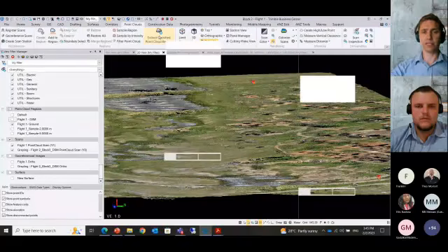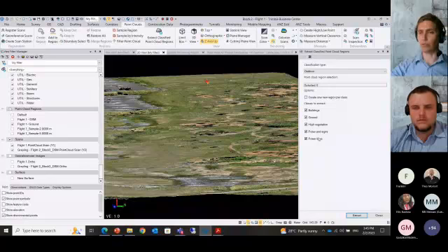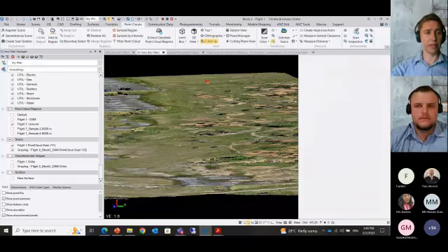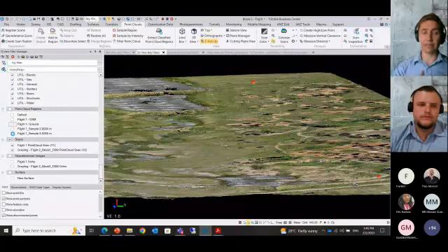If you click on this function, this is where you will take your complete point cloud and extract what you need. If you're only interested in the digital terrain model, for example, you just select ground and you run that process, and then what will happen is that you will generate a point cloud. What we also did was we sampled the data set.